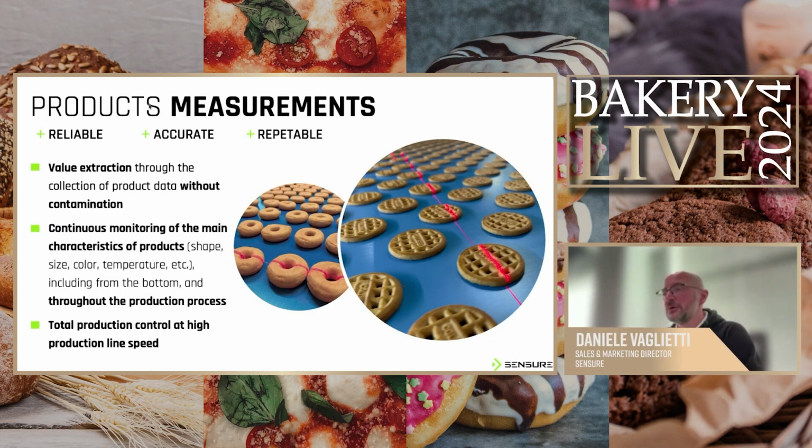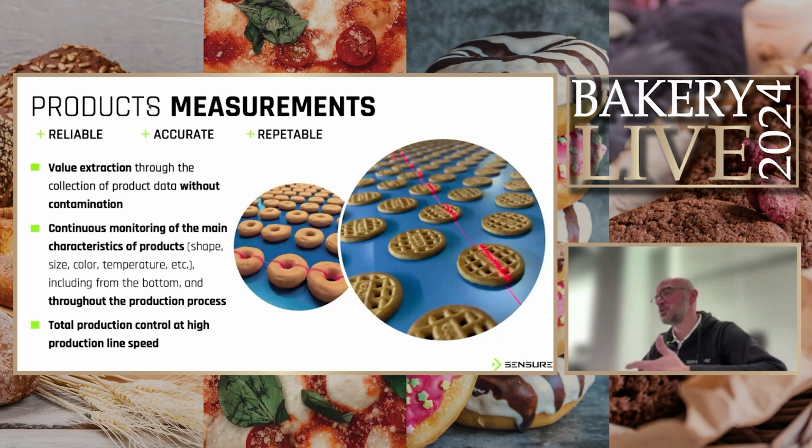Of course, when you need to take these measurements, you need to take into consideration many things. When you mention a vision inspection system to collect the data, you need to know, of course, the speed of the line, dimension, the lighting, external lighting, and so on. And you have also to consider that today there is the possibility to measure the product even on very fast lines.